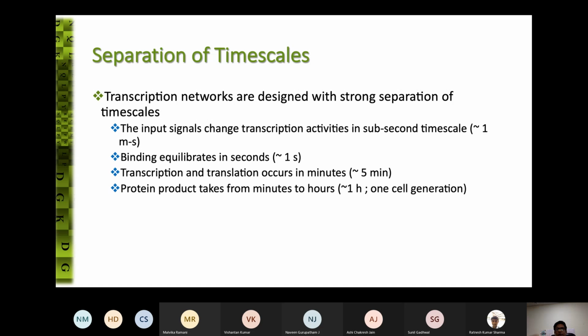Let's say if I were expecting oscillation, I see that also. But if I mix or start varying one of those parameters, which have been tuned for the entire system, then I find difficulties in converging or I'll find inconsistencies in the response. And there is no way that you can fix it really, except that you go back and use values which are close to those, within 10% of those values of the parameters. Else sometimes they'll just give you an anomalous result. So keep that in mind.